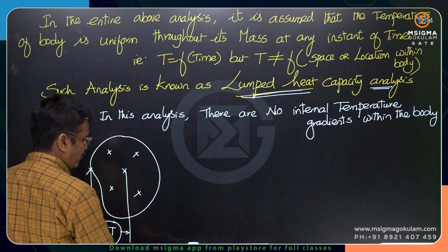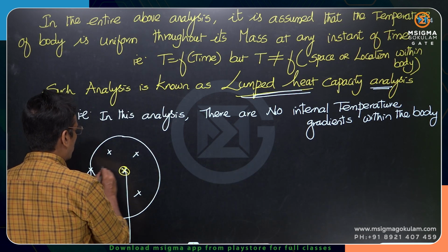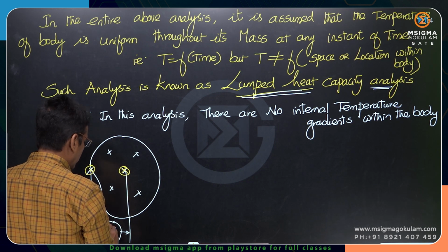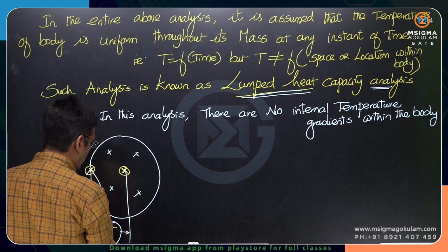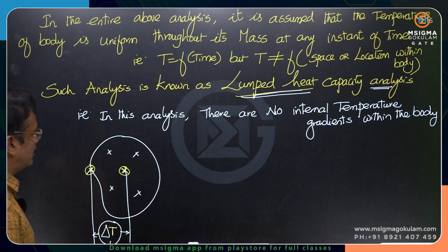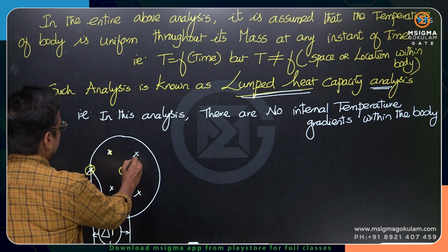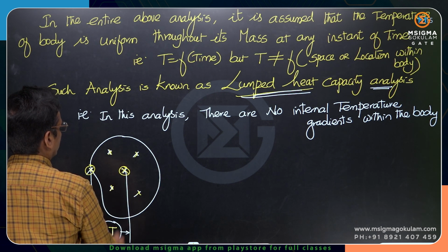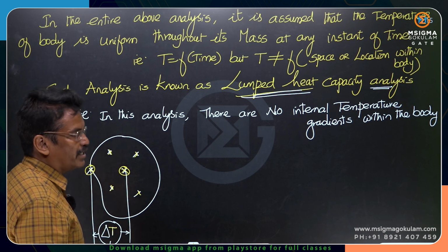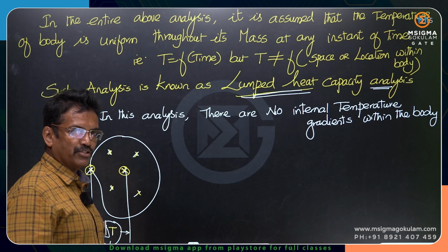That kind of analysis, where all locations have the same temperature at any instant of time with no internal temperature gradient, is called lumped heat capacity analysis.